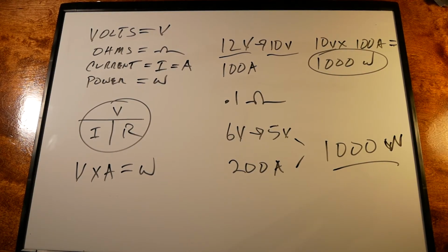So interestingly enough, whenever you double voltage, you reduce your current requirement by half. So when going from 6 volts to 12 volts, our cable went from 0.42 inches to 0.33 something. Significant decrease in diameter. And that relationship holds true even at much higher voltage levels.